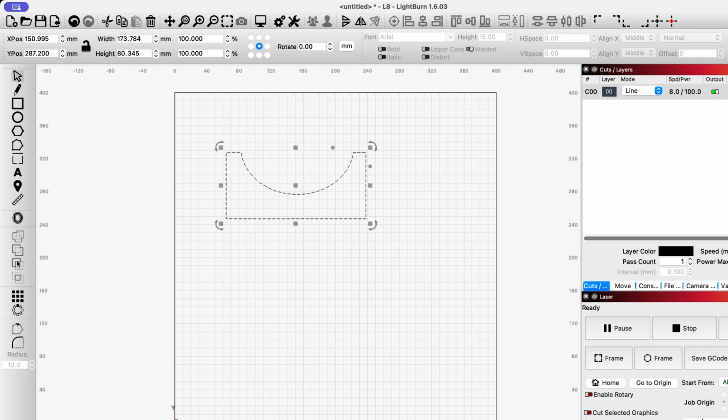We can do this one. That will take it away. So there you have this. And of course, I would have made sure that I had it centered too. That's another tip: always make sure, if you want this in the right spot, that it's equal. So I just did that, and then you hit the Boolean tools. Sometimes it won't work the first click. You have to undo and redo it. So here's like if I was doing a tray or something.